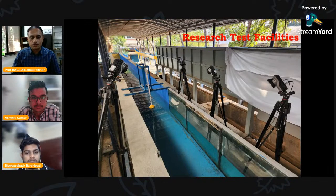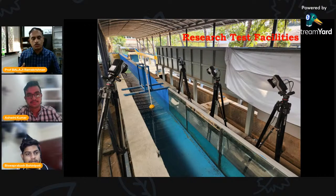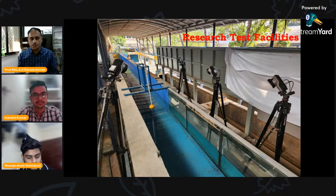Over the years, we have established quite an interesting range of research test facilities. What you are looking at on the screen at the moment is what we call a wave flume or wave tank. This tank is 50 meters long, with a 1 meter by 1 meter cross section. In this photograph we are not able to see it, maybe in the next photograph, but we have a computer controlled wave making system installed in this tank. It can be controlled using a syntax, or what we call a protocol, through the computer, and it will generate waves in the water tank exactly as you intend the structure to be subjected to.